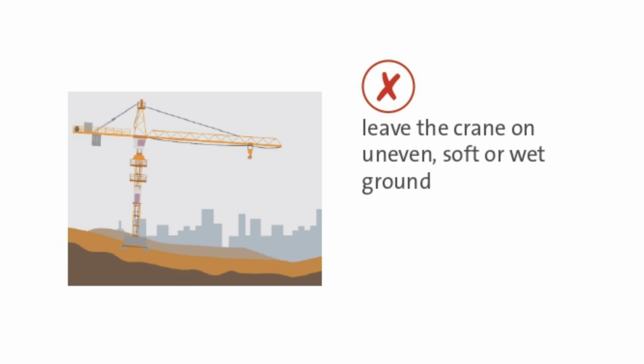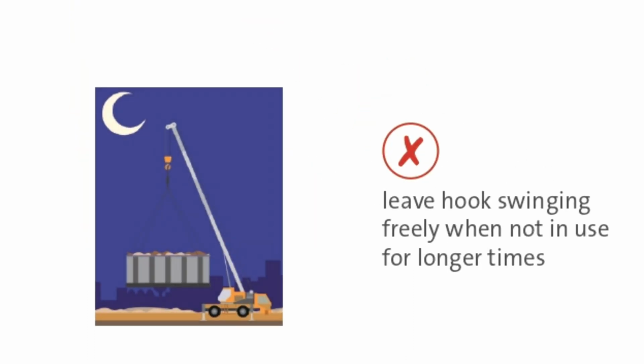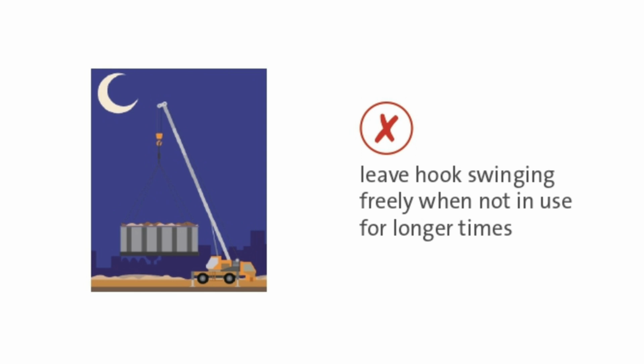Don'ts. Leave the crane on uneven, soft, or wet ground. Leave keys in the ignition when the crane is not in use. Leave hooks swinging freely when not in use for longer times.